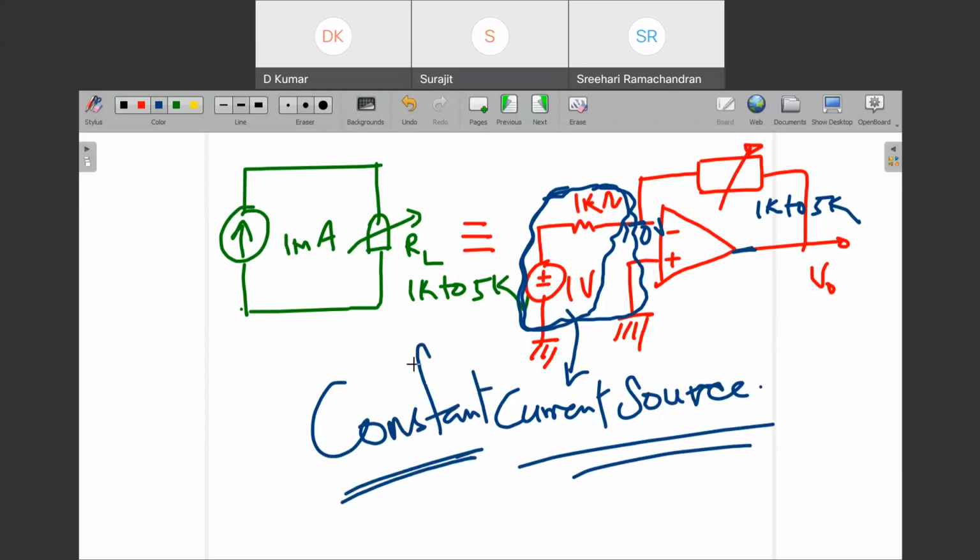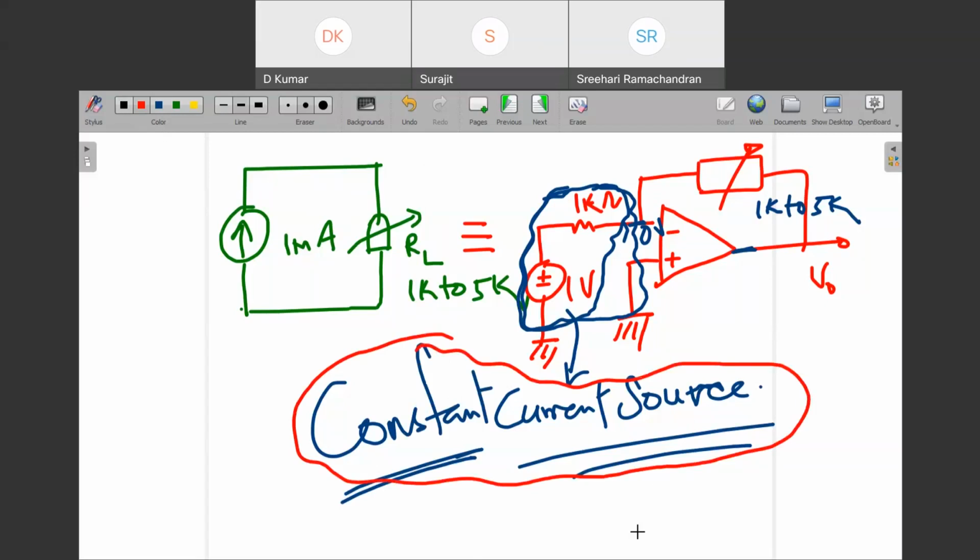And we are designing a constant current source so that it can charge the capacitor linearly. In case of an integrator there will be resistance and there will be capacitance. So unless a constant current flows through the capacitor, it cannot charge linearly. Understand? Regarding stability and all, we can't comment here, right? Because in what sense are we commenting? We are just trying to build good current sources and ideal current sources, because in reality we can't get a constant current source, right?